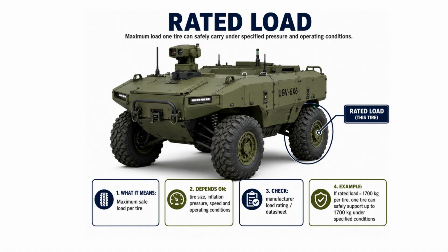Rated load is the maximum load that one tyre can safely carry under specified operating conditions. These conditions include the correct inflation pressure, approved rim, operating speed, tyre construction, and the manufacturer's recommended usage. For example, if a tyre has a rated load of 1,700 kilograms, it means that one tyre can support up to 1,700 kilograms when all specified conditions are satisfied.